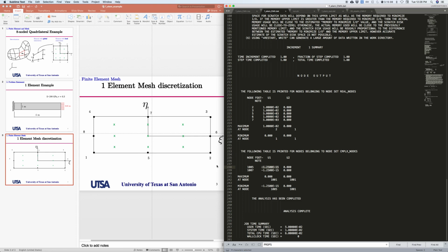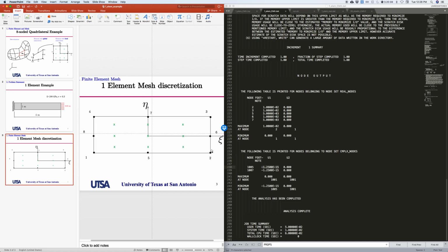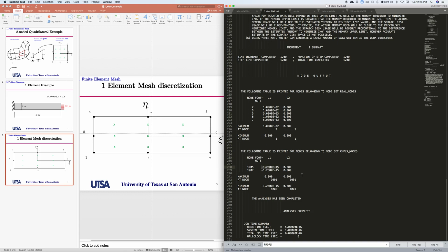If you were to verify this derivative using finite difference, how would you do it? You take these 3 nodes and you just perturb them a little bit, right? So you make the beam a little bit longer. Instead of being 4, it's going to be 4.001 or something like that. We are doing the same. We are perturbing those nodes, but we are perturbing them in the imaginary direction. So actually, yeah, you have one derivative over there.